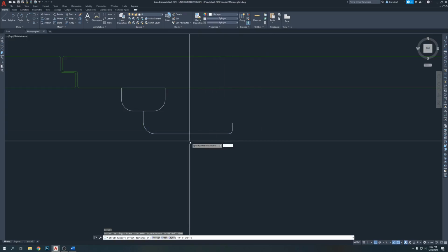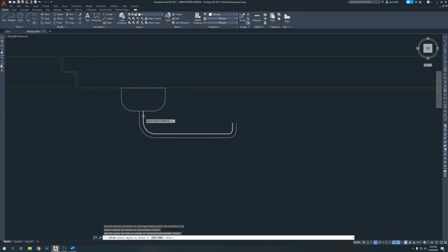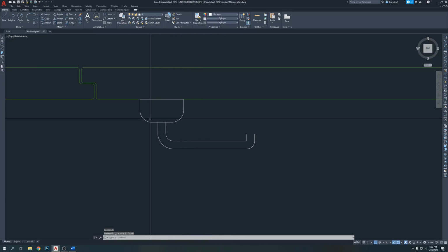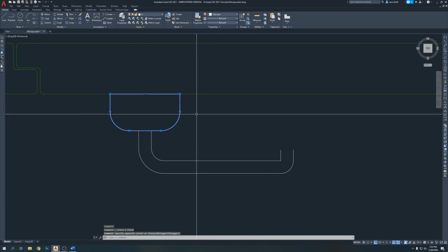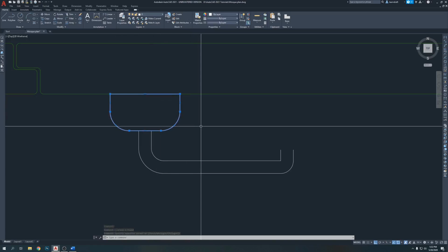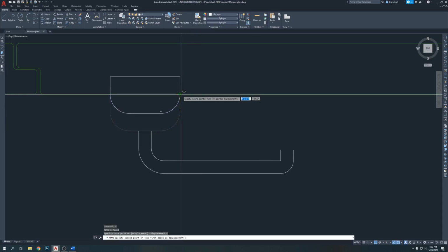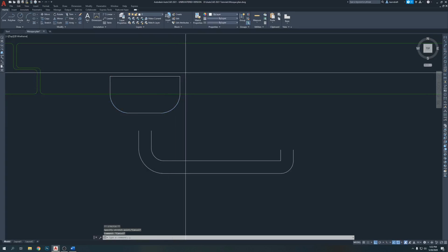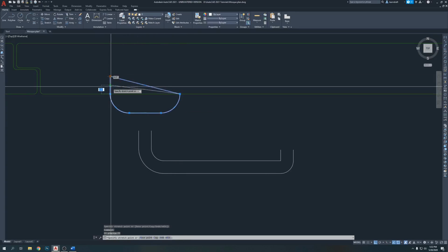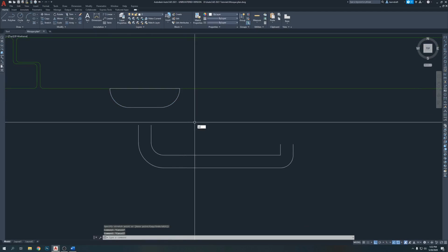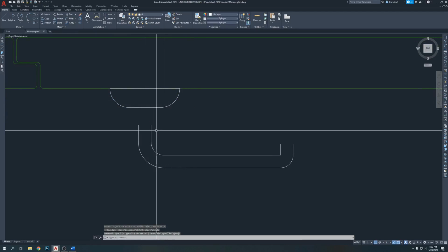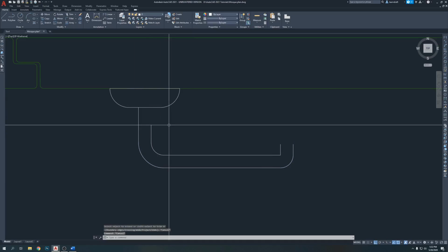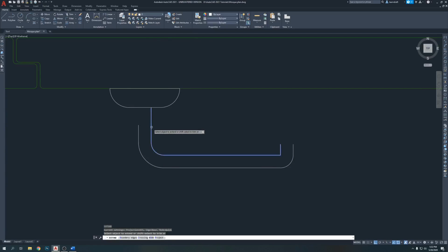Offset 0.25. Okay, actually this frame looks like it is too big. I'm going to push it inside, hold it from this corner to there, and bring this one, click here, there, click here, there. Extend this line. Extend, EX, just click on the line.